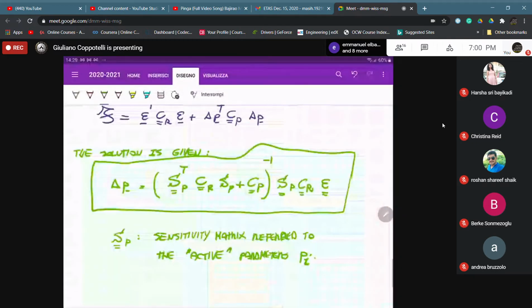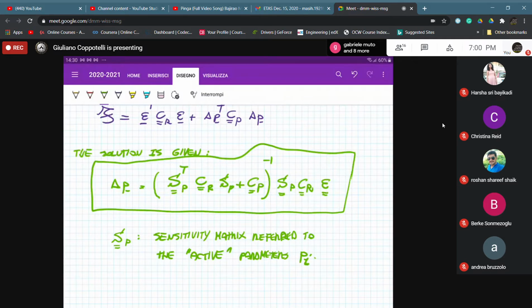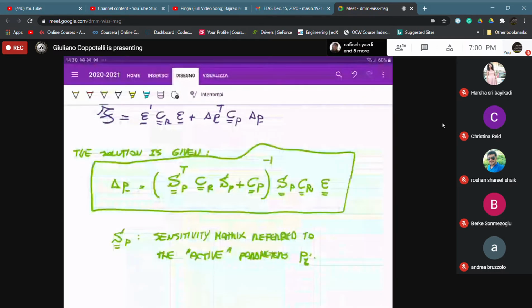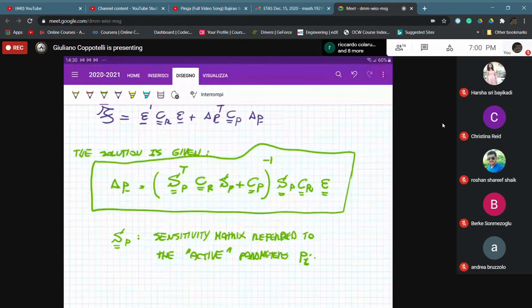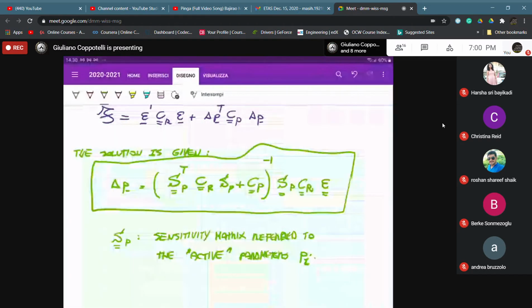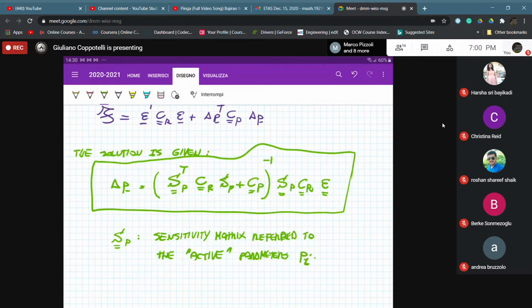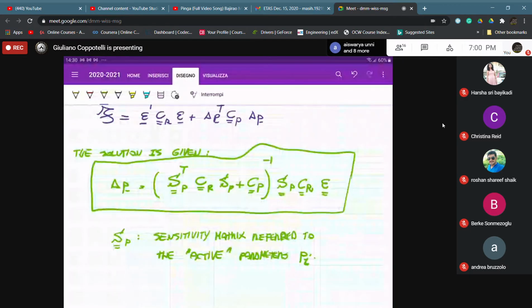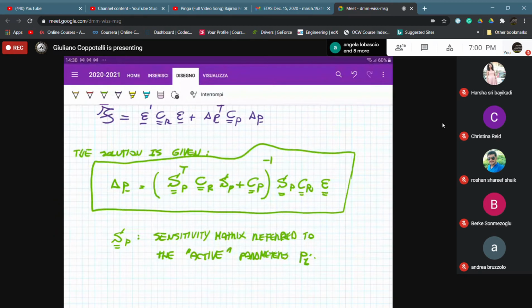What does it mean? It means that in this approach we can define an alternative scheme that allows you, iteration by iteration, to get the change of the design parameters, introduce the new values of the design parameters into your numerical model, evaluate the new response function, that is the new FRF, and then recompute the correlation function and start again with the procedure until the change of the design parameters is no longer important.